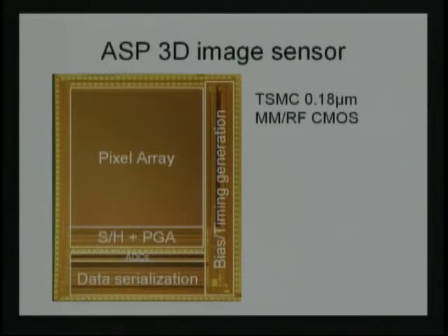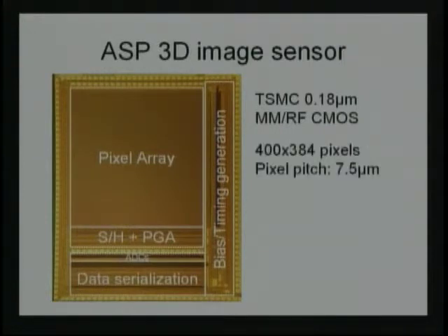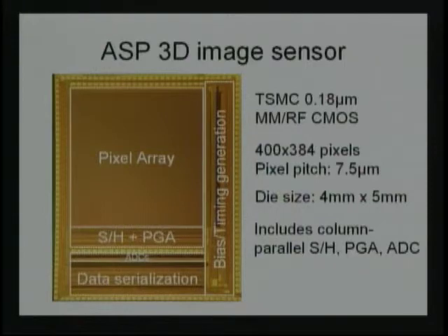Okay, so to actually do this, of course, we need a chip. So we designed a large, for us, array of these pixels. This is about a 300 kilopixel sensor. It has various circuitry on it as well. That's one of the nice things about being in CMOS: you can incorporate not just your optics, but also all of your electronics. And it's all essentially 100% reliable, provided you design it right. So we've got a set of pixels, but we've also got various sample-and-holds, amplifiers, and so forth.